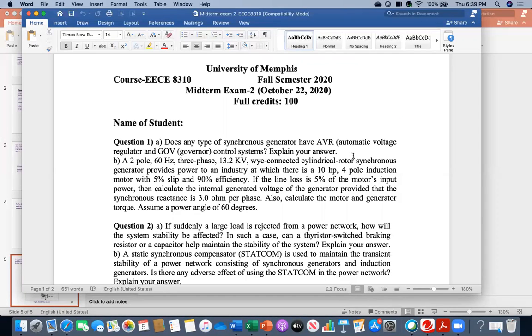These days as an engineer, if you choose between a conventional synchronous generator and the PMSG, you should choose the PMSG. The reason is that if you use the PMSG, then you can avoid the AVR system, because it is permanently magnetized. So you don't need any excitation, and consequently you don't need AVR. What is the function of the AVR?